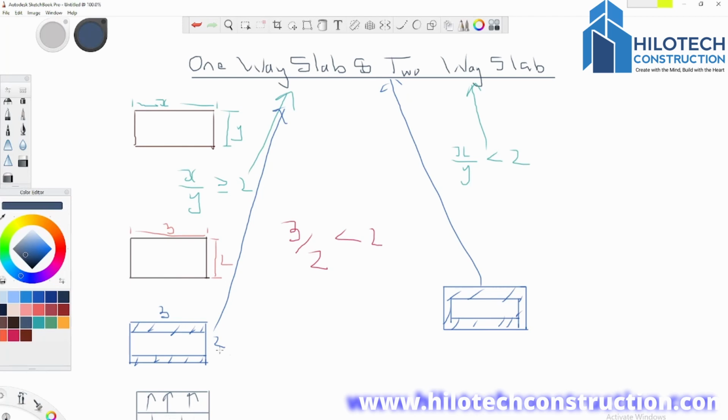This one you can easily see from what we call the yield line theorem, for those of you who have done that. And for a two-way slab, it is going to be like this, and for the load distribution, you're actually going to have the load like this on all 4 sides. So you have the loads like this, on all the 4 sides. So this is a one-way slab in terms of the load distribution, and this is a two-way slab in terms of the load distribution.